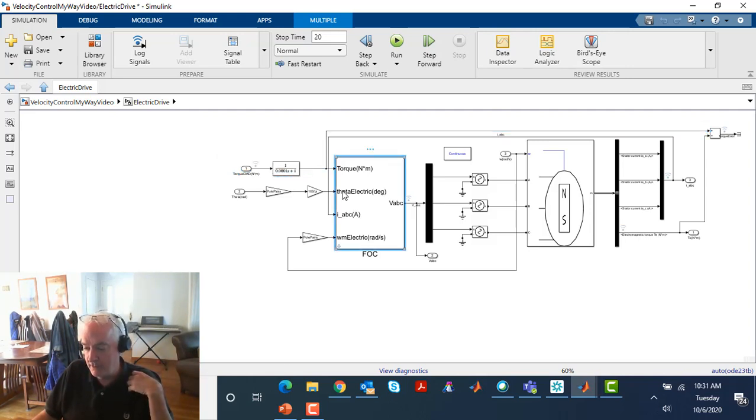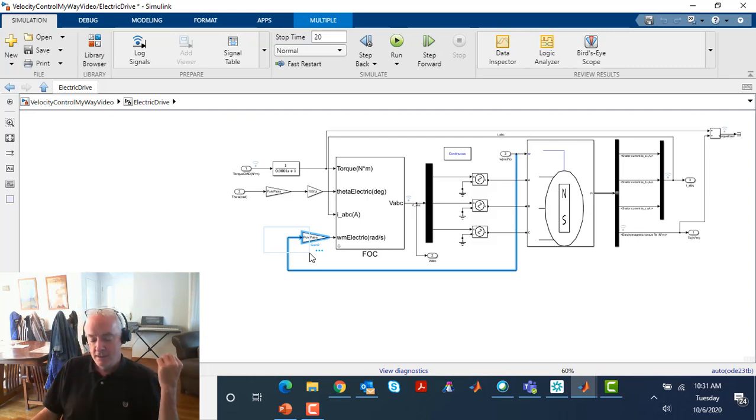Okay, so I'm very excited by that as I learn about field-oriented control. Now, with regard to the rest of the algorithm, it works based on observation or feedback. We feed back where the shaft is, and that will be the angle. You'll also see something that might appear redundant: we're also feeding back the angular velocity. Sure enough, we could put in some numerical approximation and a derivative so that we never even need to think about it, and we reduce the amount of feedback. I'll just say sometimes you want to be a little more intentional than that, and you give yourself more options.